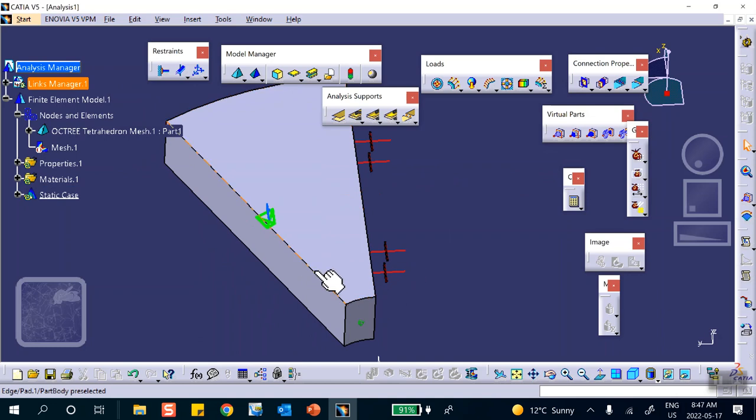On this face, instead of putting a surface slider, I want to say nothing moves perpendicular to it. But perpendicular to it is not x or y or z. So I'm going to create a local coordinate system here. This is why I have to go back now. Because you can't put that coordinate system in here. I have to go back to part design. And before I do that, let me save this.